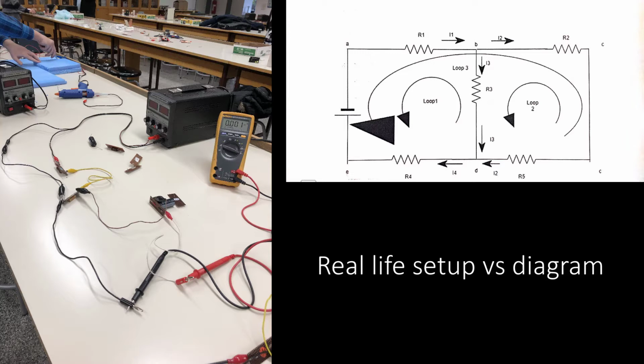Then, results are compared to the theoretical value of Kirchhoff's junction rule, and the error value is added to table 1. The same steps are applied to junction D, but this time current values between BC, BD, DE are observed through the multimeter, and results are noted in table 2.